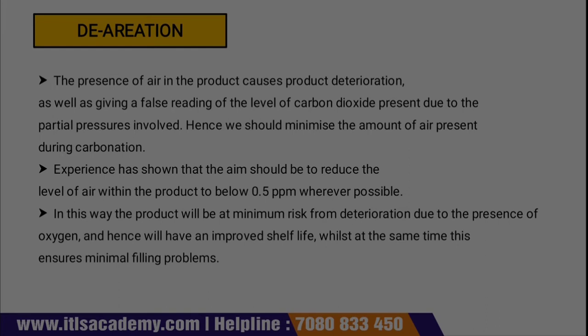Hence, we should minimize the amount of air present during carbonation. The question that can be made here is why there is a requirement to minimize the amount of air present during carbonation. So, what is the answer? The presence of air in the product causes product deterioration as well as giving the false reading of CO2, means the level of CO2 present due to the partial pressure involved. Hence, we should minimize the amount of air during carbonation.